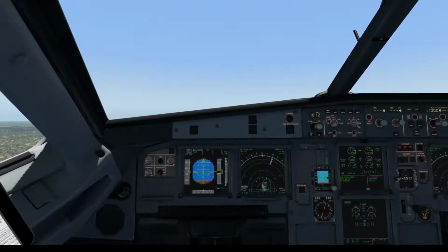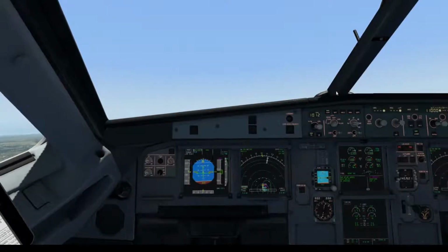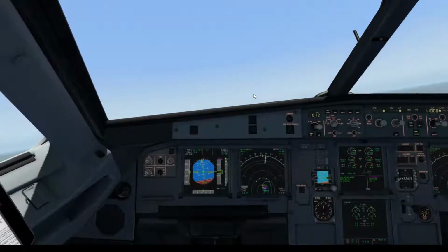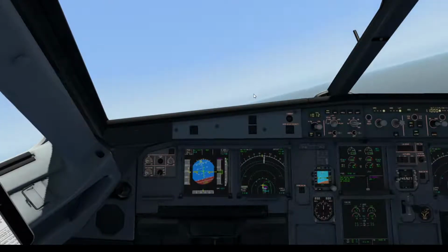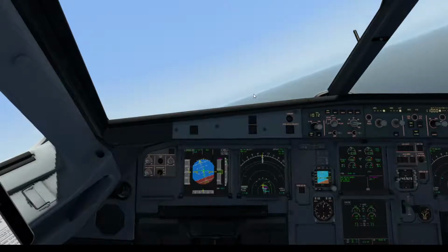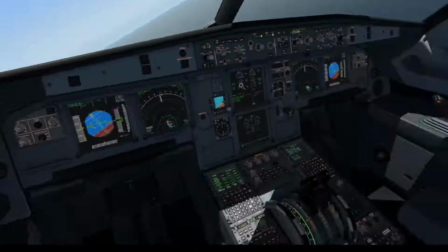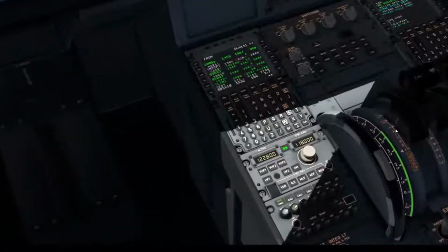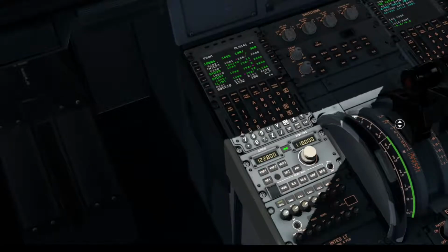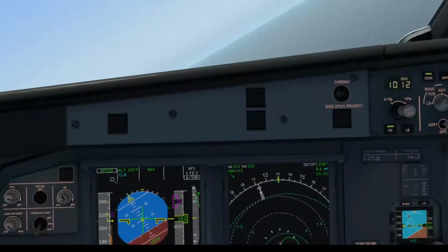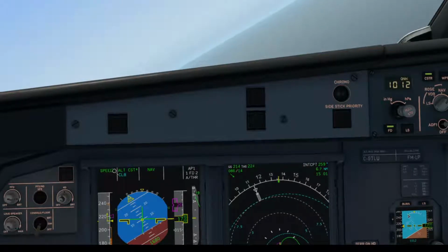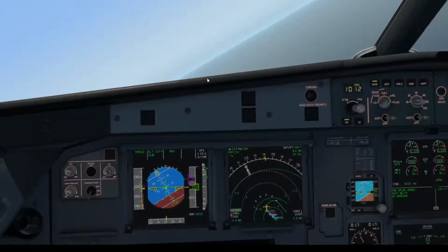Flaps up. We see lever climb, that means pull back throttle. Autopilot 1 engaged. Right, we've pulled back the throttle so that it is lining up with this detent. At the same time you can see the value here change to speed.